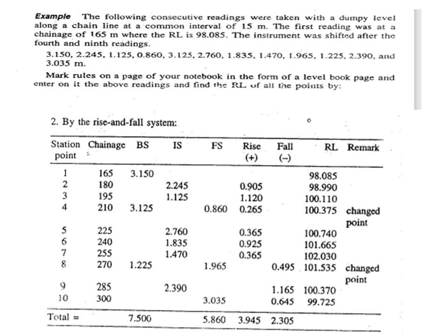Two adjacent planes of collimation are correlated at the change point by an FS, that is the foresight reading from one setting, and a BS reading from the next setting. It should be remembered that in this system the RLs of unknown points are found out by deducting the staff reading from the RL of the height of instrument.